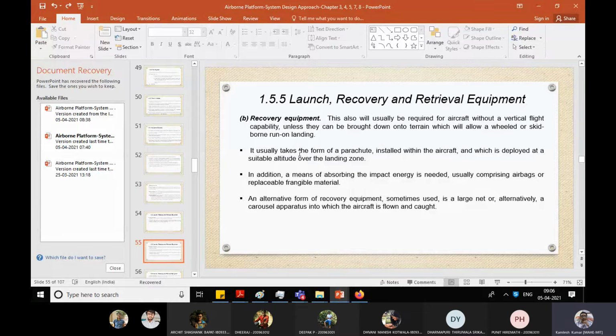And once you are coming down, there are variations of the mass, CG variations, and till you reach the ground, what you will see is your airbag will go down, and the complete aircraft will be in wing level. Okay, so it's not touching with any wing tip, not touching with the tail, not touching with your nose of the aircraft. It comes down on what's called the airbag system, and stays level. Okay, so people are testing this for small UAVs, I think 5 kg, 6 kg, they have already tested this type of design.